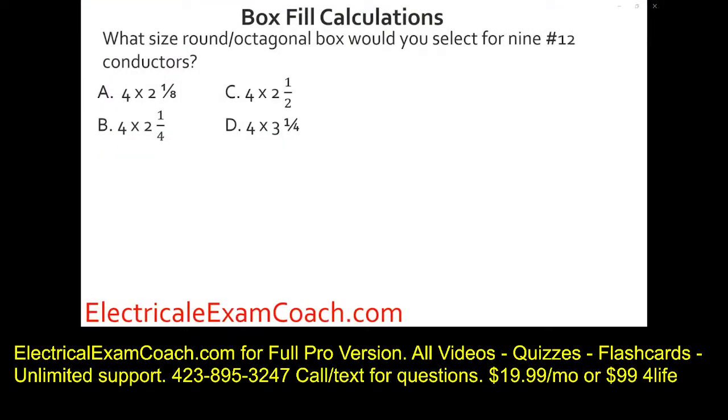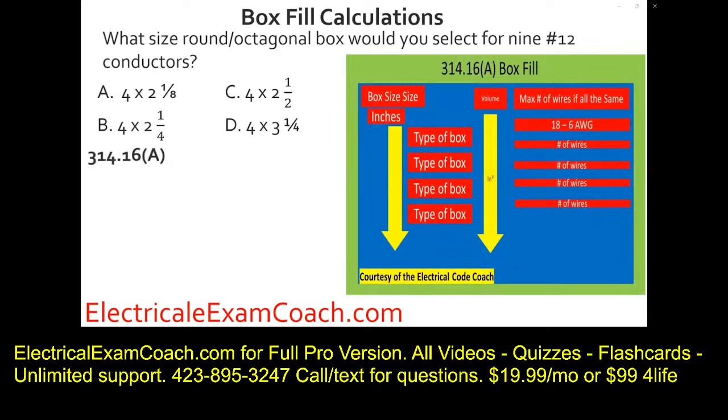What size round octagonal box would you select for 9 number 12 conductors? For this one, we're going to be using table 314.16a. We're going to start here and we're going to find our gauge of wire. Then we're going to come down and we're going to find a box, making sure to cross over and double check that we don't cross over into a different style box. We want to stay in the round octagonal. We find our conductors, we find the one that fits it, we slide over and double check ourselves, and we're going to select A. Great job!